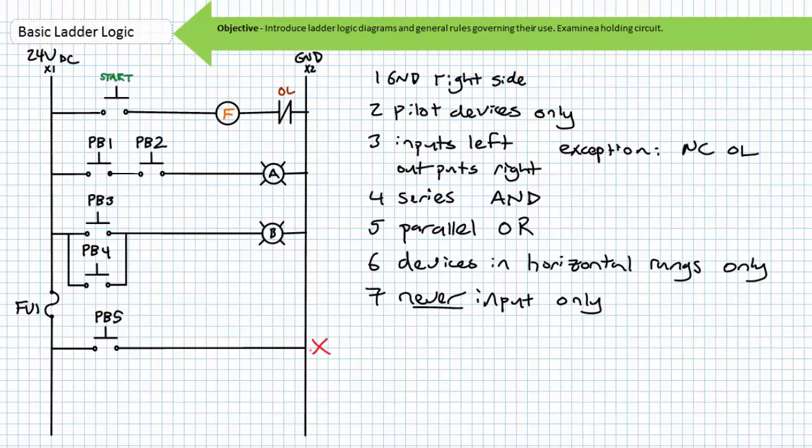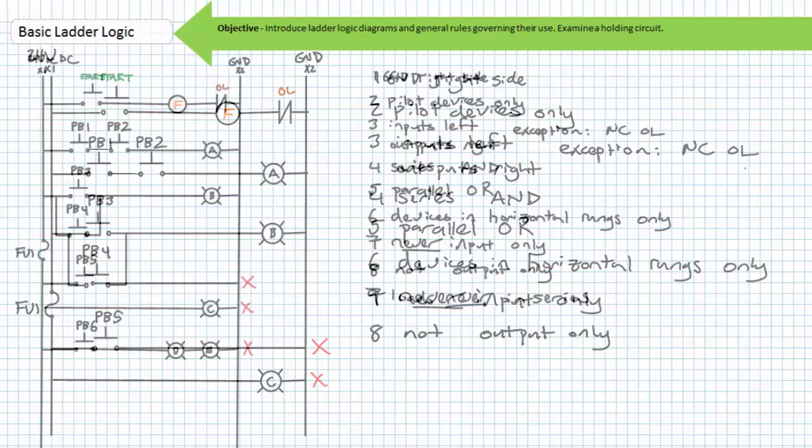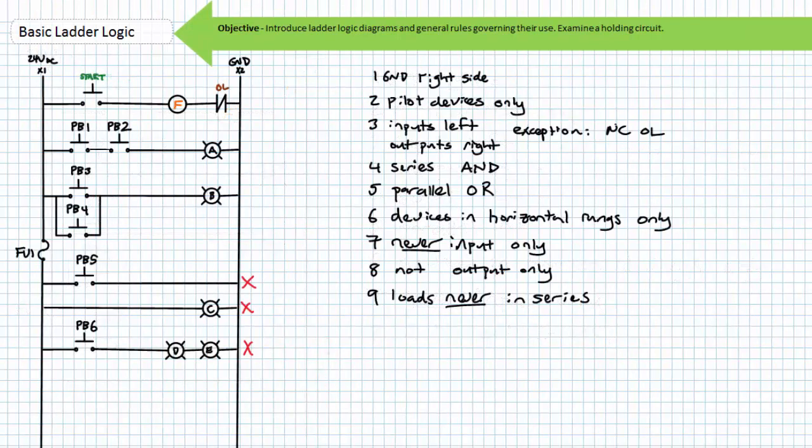This is all sorts of wrong. This is to suggest the maxim that all rungs must contain one electrical load. Similarly, load devices aren't ordinarily directly connected from one vertical upright to the next, unless you want that device continually energized. Lamp C would always be energized. What's the logic in that? Our diagram and list is getting a little bit long, so let's go ahead and give ourselves some room.